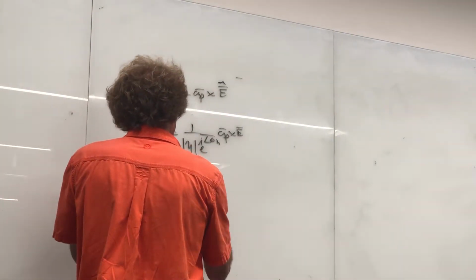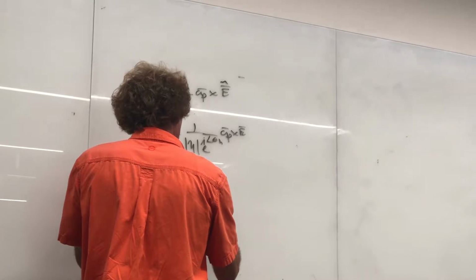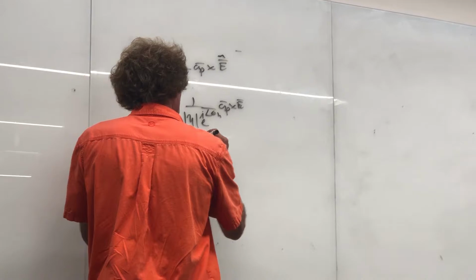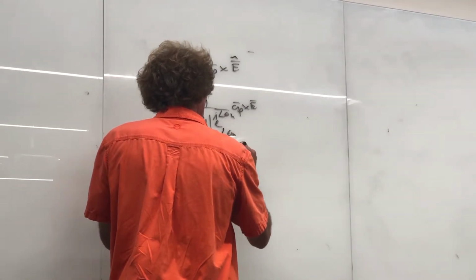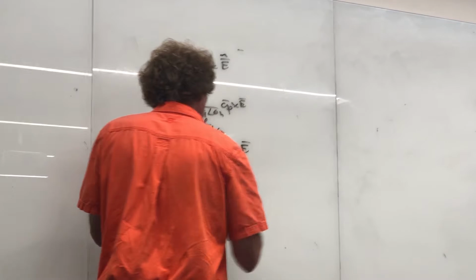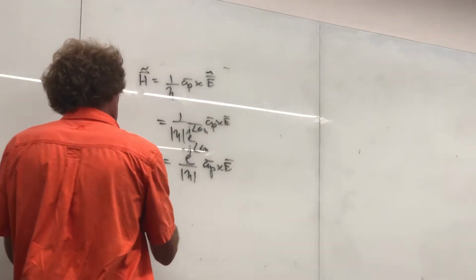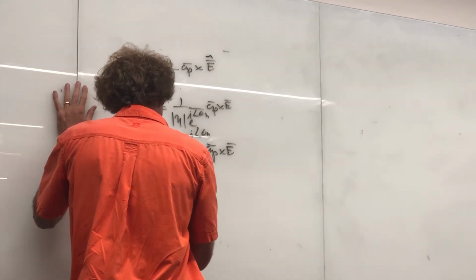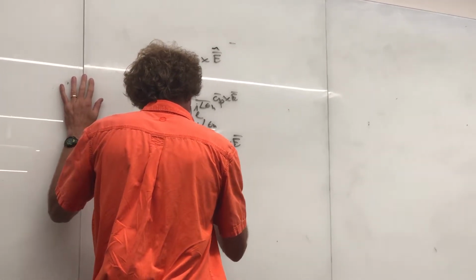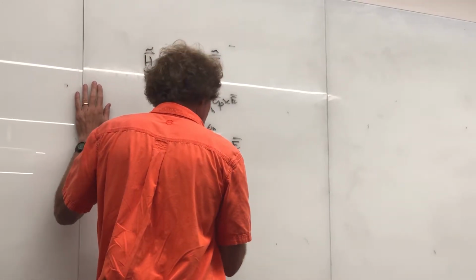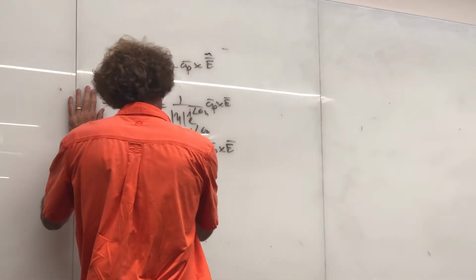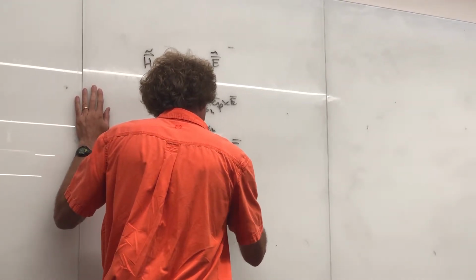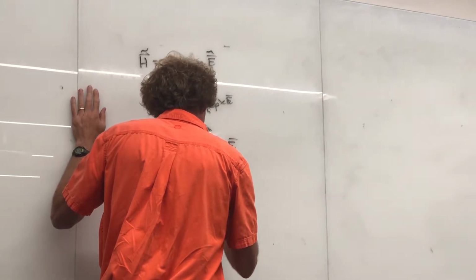That also means we have 1 over the magnitude of eta, right? And then when this phase comes on top, it becomes e to the minus j phase angle theta n, A rho crossed into the E field, right? And that's still H. Now if we want the time domain form, H becomes the real part of e to the j omega t times H phasor. And that would be times e to the minus j phase angle theta n over the magnitude of eta.